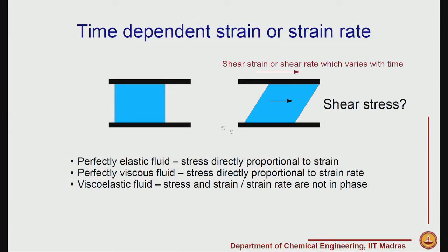So, again going back to the colloidal system that we thought of, where there were clusters and network of clusters, what we can see is when we shear the system continuously in time, the clusters also get adjusted based on the deformation being imposed. Therefore, the overall property of the fluid that we observe will depend on the magnitude of the shear strain amplitude or of the shear rate which is being imposed. So, in all these cases it is always helpful to go back and look at the microstructure of the material.